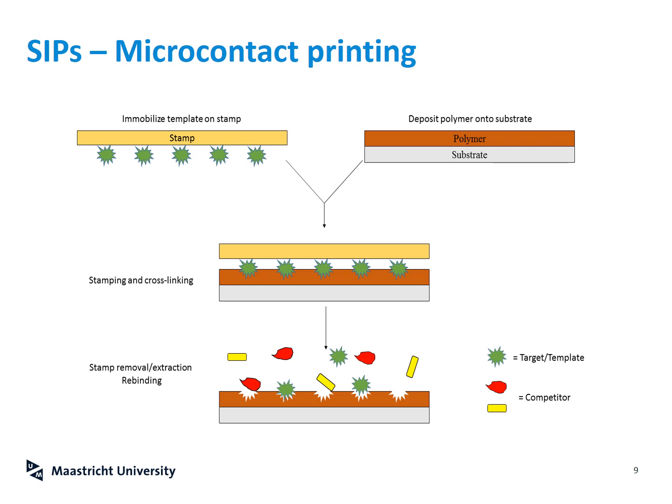with functional groups on the surface of your target. These can be proteins that are specific for a bacterium. These can be carbohydrates that you have on a bacterium. In any case, it will create a functional match next to the already existing morphological match. When you then expose these MIP covered chips to a complex mixture of small molecules and bigger entities, only the E. coli will bind to your layer and will cause a signal.